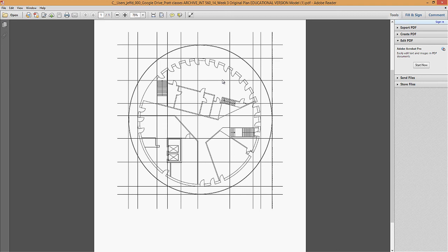So in class, I'll often ask you to plot to a PDF file. This is a very common way of plotting drawings and sending to someone without having to send your drawing files, with your associative files, your CTB files, etc., for them to plot. So instead, when we plot to PDF, we're plotting what would look like a drawing from a normal paper plotter, but instead it's a digital file. The Adobe PDF is a defined plotter in your printer list if Adobe programs are installed on your computers. PDF files are vector files, so they can be used in Adobe Illustrator for modifying, and the lines, the vectors, will be maintained, and we'll see that in a later lesson.